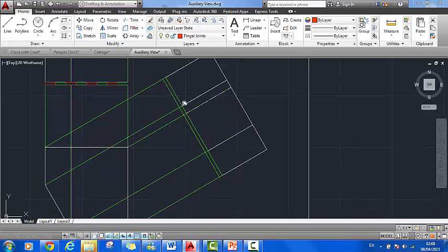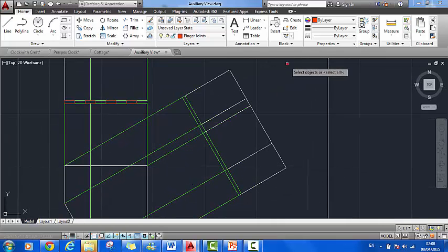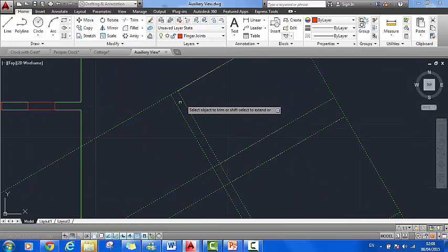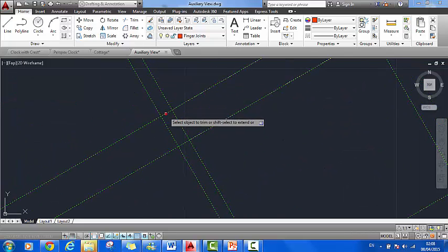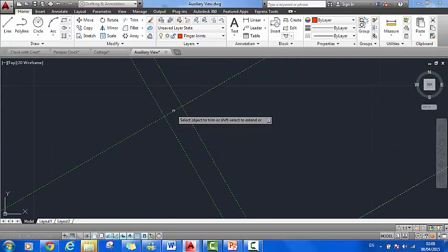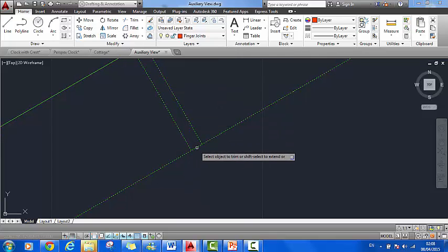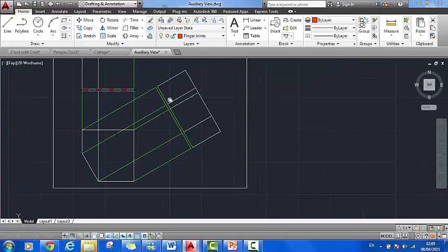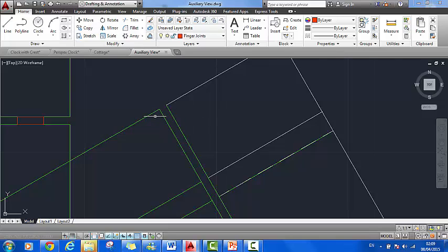So I want to begin by trimming the green line in between the original X1, Y1 and the 3mm offset. Take note, I always start at the left hand side. This will be important for recreating the finger joints for the plane later on. So I'm in my finger joints layer, up to create a line again. Do the same as what we did for the elevation. I'm also going to offset these distance of 10mm, it's already preset for us there.